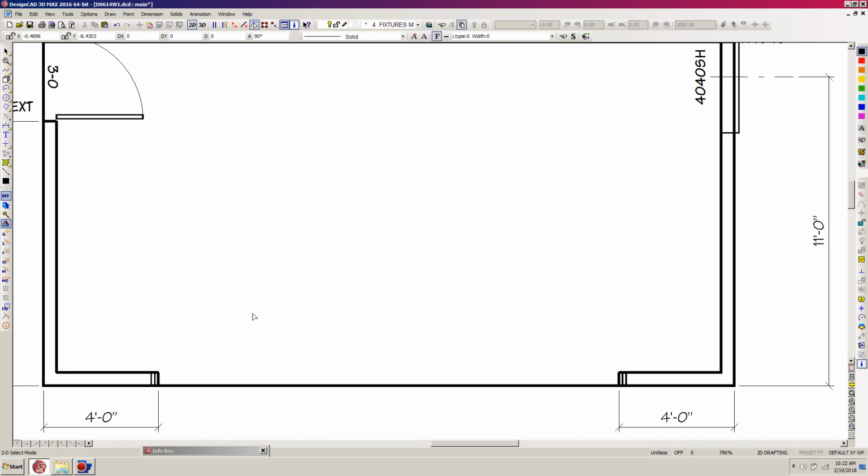So now I need to go ahead and create my beams. I'm going to show those beams at the midpoint of the wall line, and those beams extend to the outside edge of each trimmer. So I'm going to hit V for vector, and I'm still in layer 4, and I'm going to hit Control K to go to the center point of that outside trimmer. Then I'm going to hit H to toggle to orthogonal mode and come on over and right click to the outside trimmer and hit my scroll button, and I have a line there now.